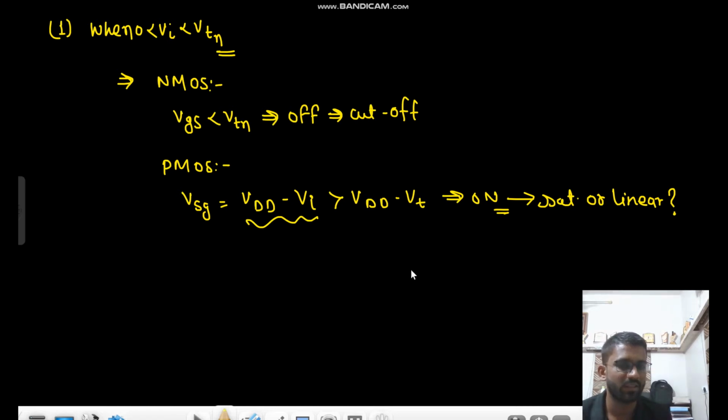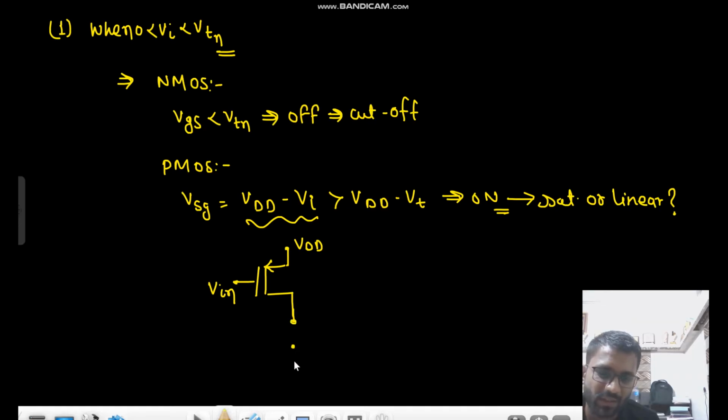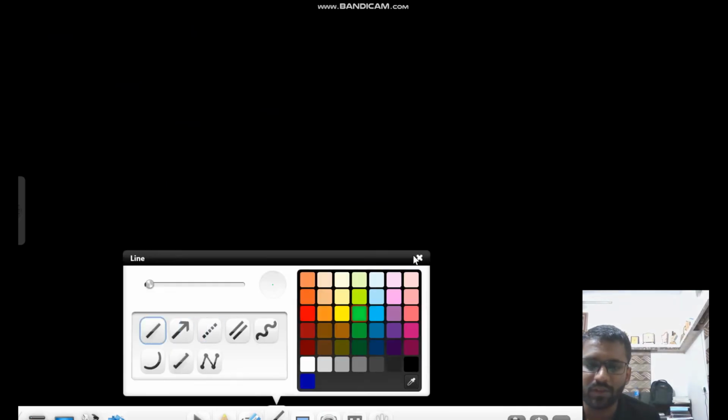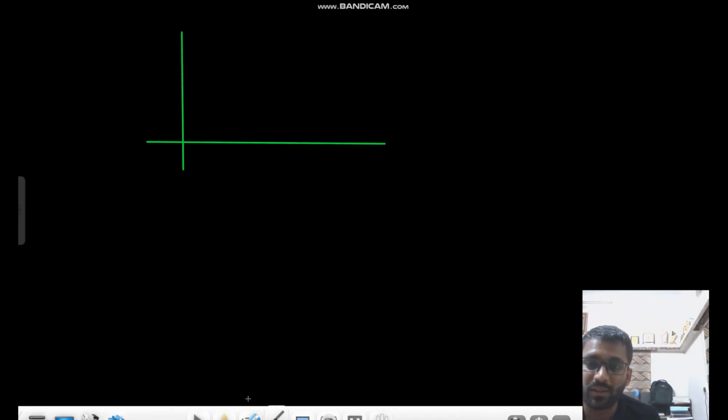So what is your answer? It will be in linear region. Why so? Let's see. This is our PMOS, this is our VDD, this was our V in, and your NMOS is open circuited and this is your V naught value. The current in NMOS is 0, so the current here in PMOS, IDP, has to be 0, right? If the current has to be 0, then what? If we draw the transfer characteristics, ID versus VSG.